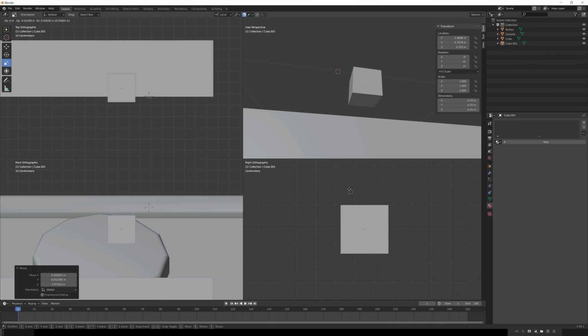One thing we can try to do is use the 3D cursor to help us out. In fact, there's actually a hotkey or a selection you can use that automatically moves the pivot point to wherever the 3D cursor is. So let's go ahead and hit Shift and right-click, and we'll get the ability to move the 3D cursor. If you let go of Shift as well, and still hold down the right mouse button, the 3D cursor is still something you can manipulate. And what we can try to do now is actually use snapping in concert with selection constraints to get this to go exactly where we want.